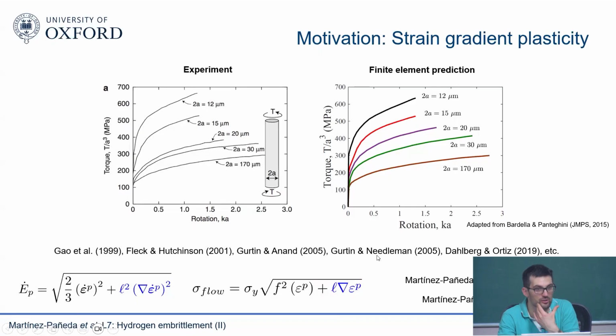But the length scale is a measure of how much extra hardening, how much extra strengthening, will come for that material for a given gradient. So basically dislocation activity. But will your L, our material property itself, change at that length scale, like with plastic deformation? Some theories include a change of length scale with plastic deformation, but I think it's easy to understand if you think of a constant value.